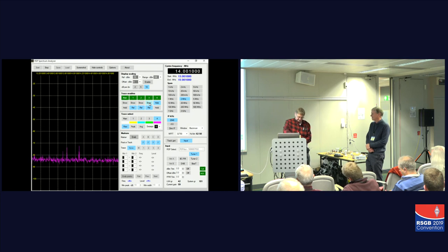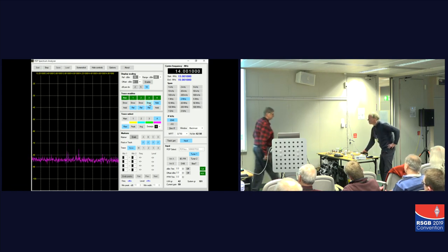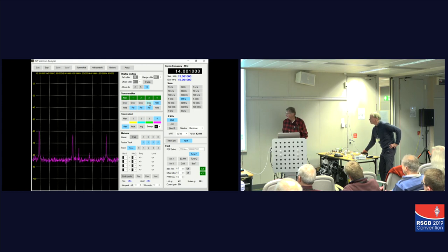I put it to one side. Eventually I managed to get the base off, and I found it was the built-in clock inside the upright of this lamp, which would show time or temperature, and it had a small switch mode power supply, which was clearly useless. When I disconnected that, which she didn't need, the LED lamp itself was fine. It was as quiet as anything.